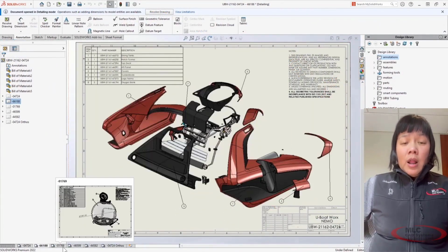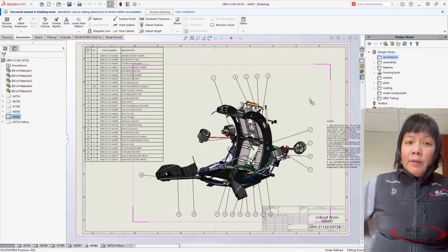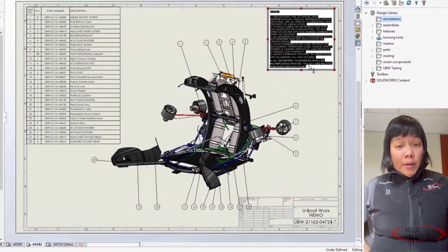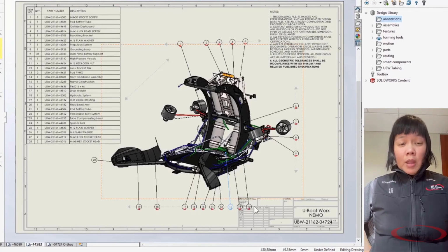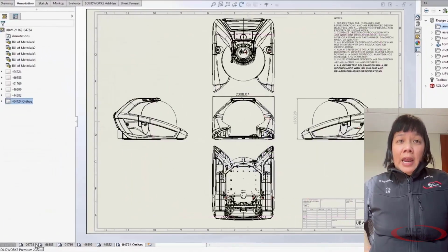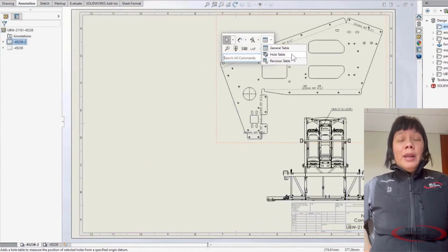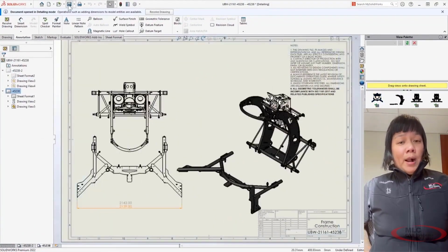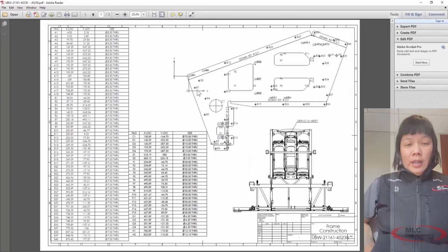For the last 3 years, detailing mode, which is essentially the lightweight versions for drawings, has been constantly evolving in SOLIDWORKS and really helps us open up our large prints in just seconds. We can even open up drawings without the overhead of loading in the reference files or even having them on our machine. So let's revisit what we can do with detailing mode today. You can add balloons, edit notes, organize sheets, add dimensions, and set tolerances. That's a lot. But in 2022, we've inserted the ability to insert whole tables and standard views from the view palette. You can even print and save a completely accurate PDF from detailing mode.